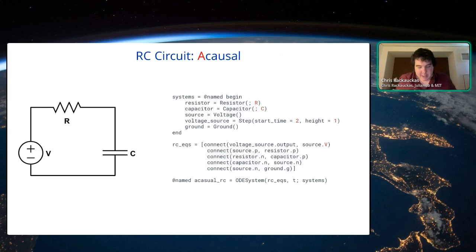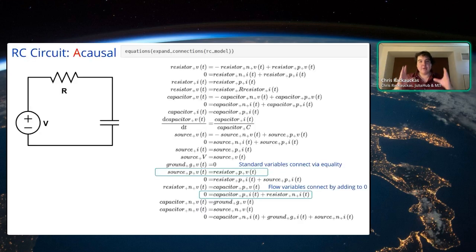When we can then connect all of these things together, what we end up with is a set of all the equations that define our complete system. Now, what does that look like? At every single possible connection point, we have to say the currents are summing to zero, so this current equals the negative of the other current, right? So the current coming out of here is the current summing into here. Basically all these things I just stated as true are what's listed here. There's about 20 different truths about our system. And so this is what we get.